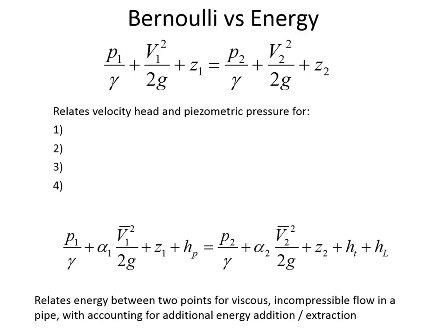But H sub L is the most complicated of all to calculate. And we'll spend like the first 2 weeks of hydraulic engineering getting the really accurate way of calculating head loss. You know, when we're using WaterGEMS, one of the first things you do is you switch it from Hazen-Williams equation to Darcy-Weisbach.